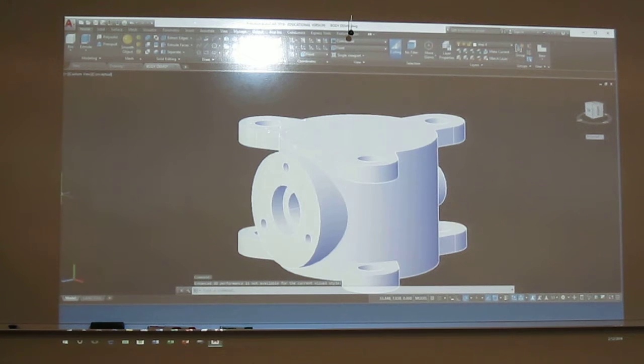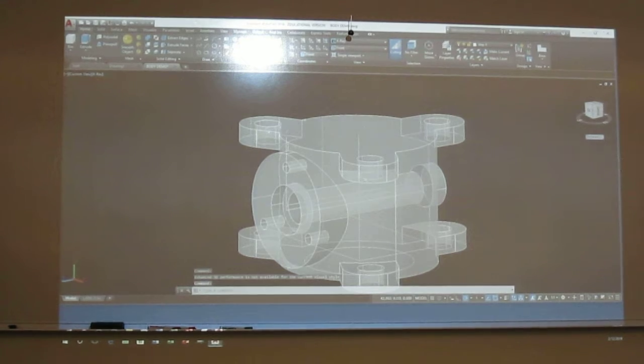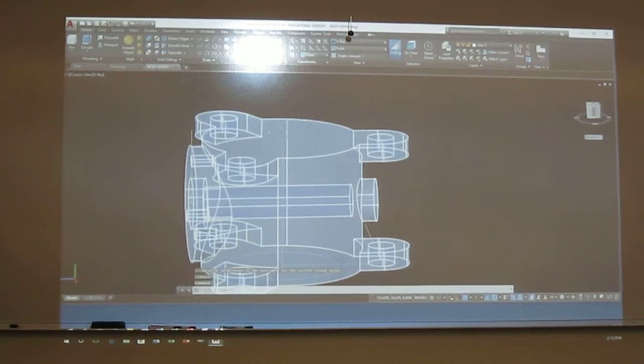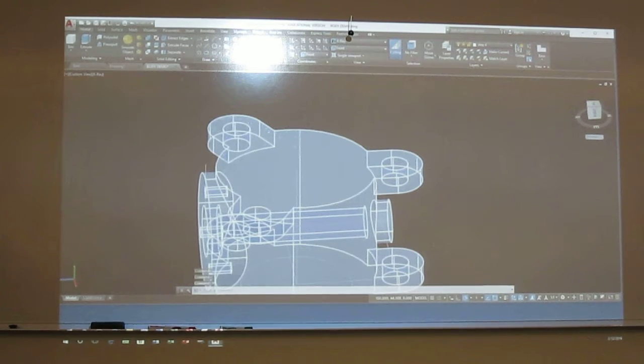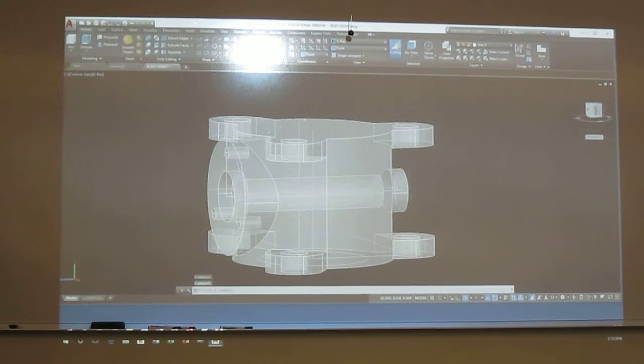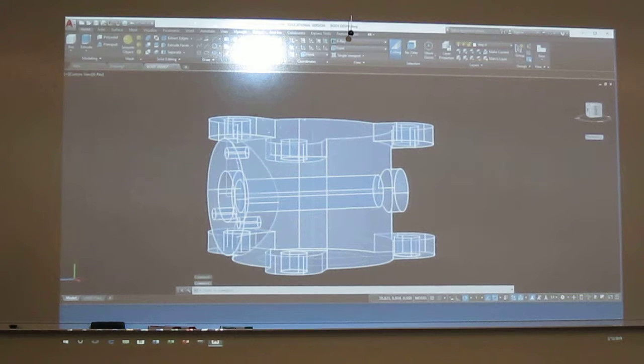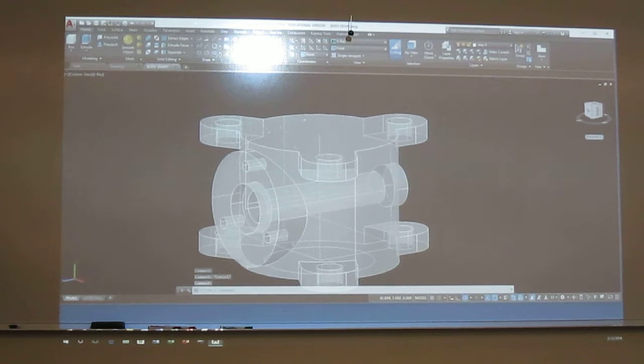Now let me switch to X-ray vision real quick. Notice where that main hole came for the shaft to fit in. Okay. It stopped. It goes past this collar, but it stops short of this guy. If I was designing this, I really don't see a need for this unless that wall thickness is a little too stout. Maybe it's there to provide some wall thickness. Or maybe we're hanging it on something, I don't know. But there's really not a reason in my mind to have this piece on here, because my shaft stops in this collar.